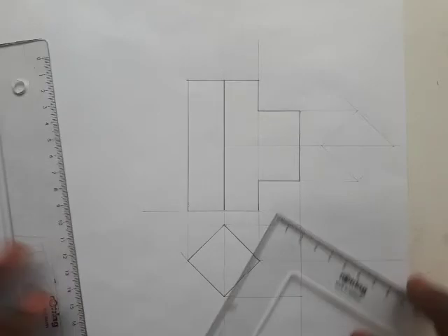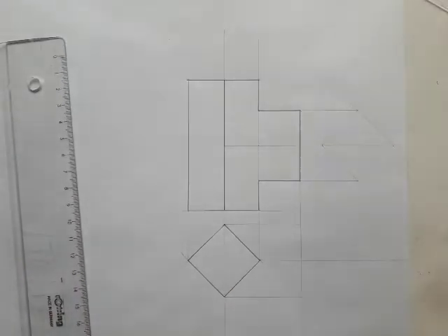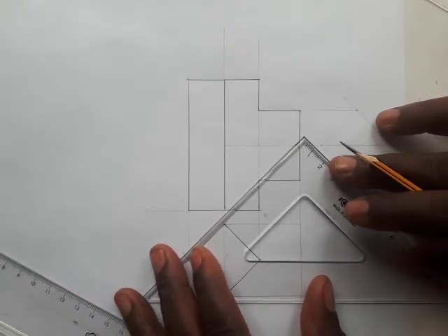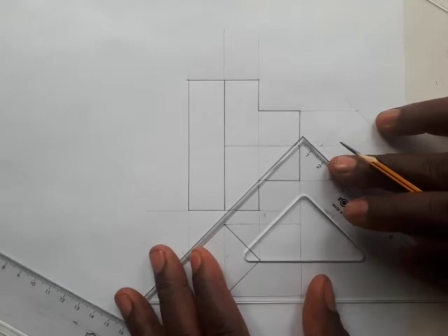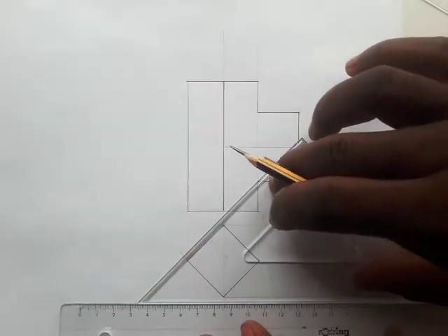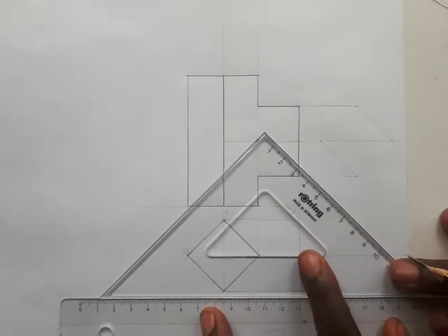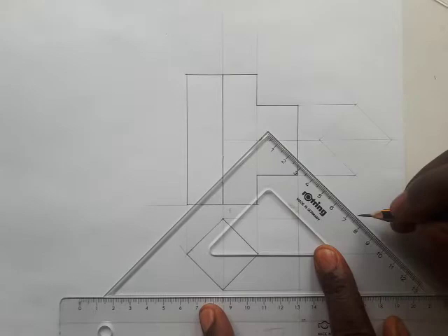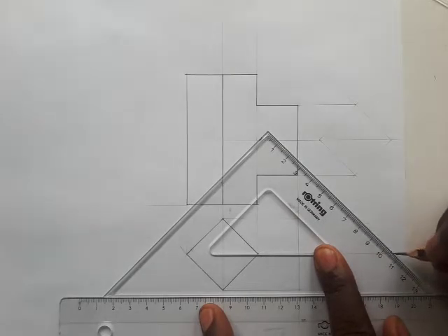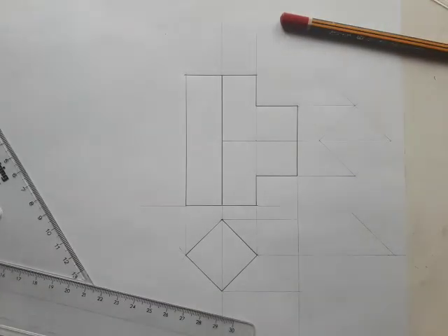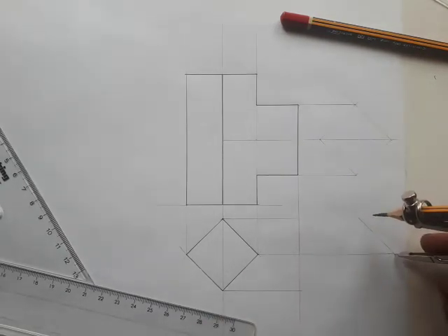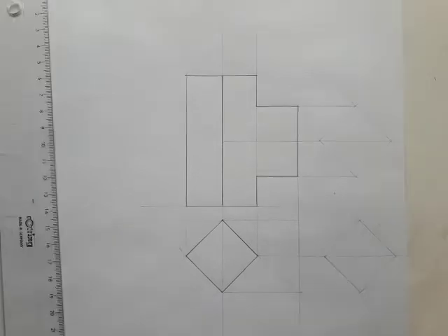But for the sake of this video, let me just do it because of beginners, so that they will understand how I got this point. So I'll just quickly do that. What I did upstairs, I'm going to do downstairs. Here I will just adjust a little bit. Remember, this is a 45-degree set square, not 30 or 60. So draw a line, and remember this is 30. Don't forget. Then you just repeat the same thing. So I'm going to do that real quick.